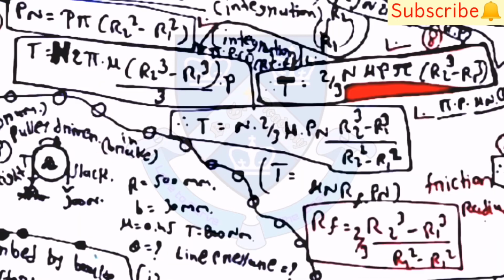Then T is equal to N into 2 by 3 into mu into Pn into (R2 cube minus R1 cube) upon (R2 square minus R1 square). Then the third equation is Rf, the friction radius. So Rf is equal to 2 by 3 into (R2 cube minus R1 cube) upon (R2 square minus R1 square).